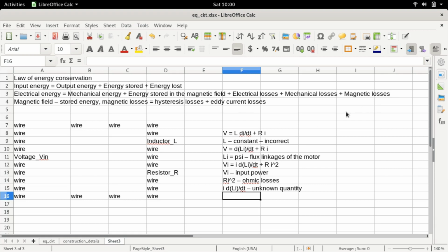The question is, when you are trying to model an induction motor, we have to make some kind of assumptions. Unless you're looking at a very, very detailed induction motor, where you want to model mechanical losses exactly, model the vibration exactly, and know exactly how much hysteresis and eddy current losses there are, you don't really need to know exactly what kinds of losses you have.